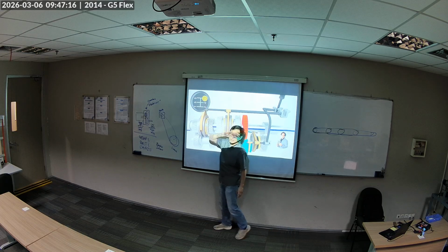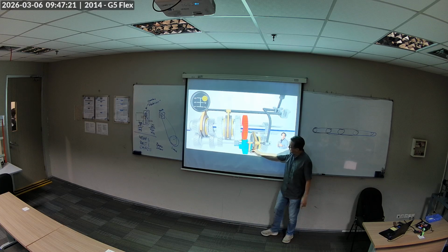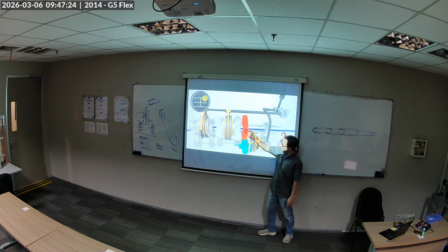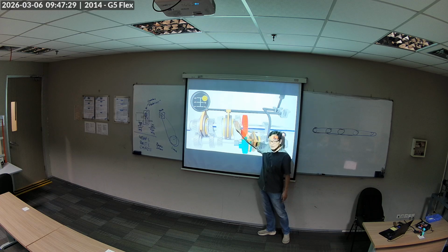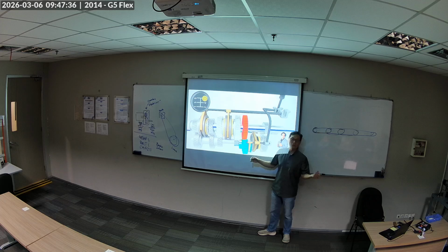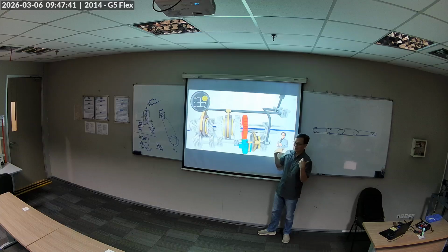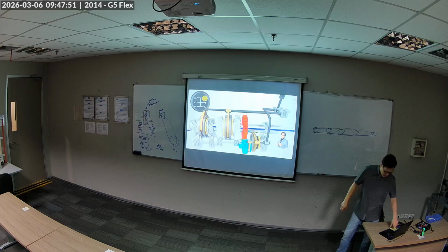Classically, in 5-speed transmissions like that. So 5th and R. Now, when you go to reverse, notice the gear is not the helical gear. We'll talk about this very soon. Okay, this is angled, and this is straight cut. And this is called a spur gear. And it's noisy. And that's why in reverse, if you reverse fast enough, you hear the whining sound. Okay, this comes from the fact that this is a spur gear. This is a helical gear, very smooth, no noise.